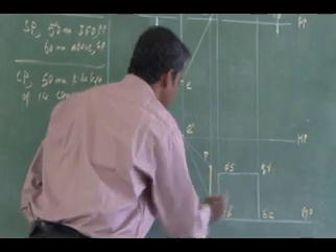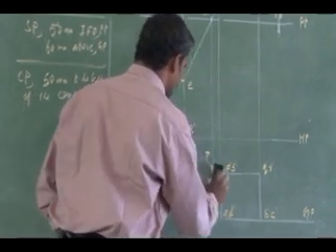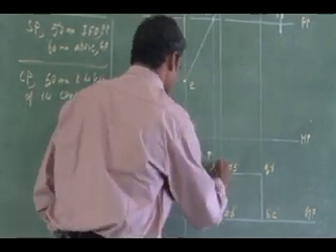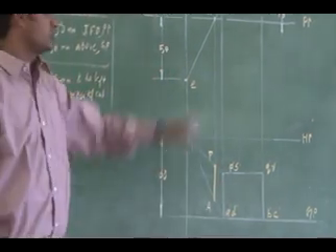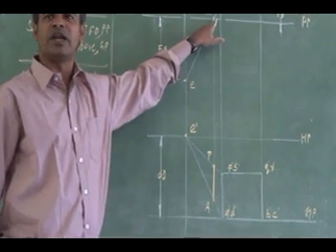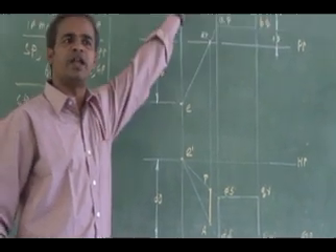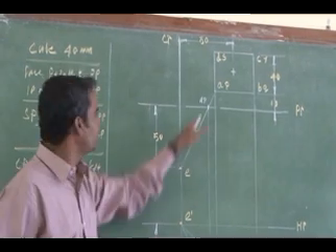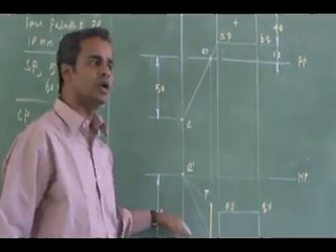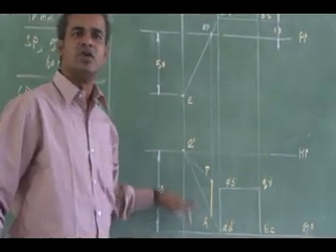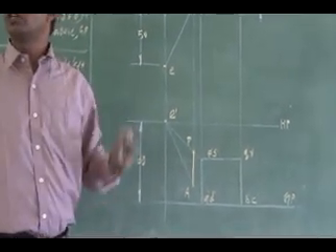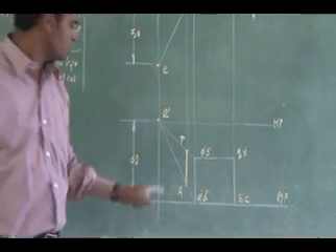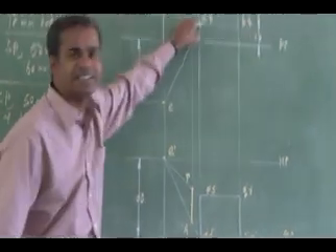This is how I have to get my perspective. First I get the intercept from the visual ray line to the picture plane in the top view. Then that intercept location has to be projected to the corresponding visual ray line in the front view. That location I mark, and that is my perspective location of the corresponding corners. Now this is the perspective view of the edge AB.